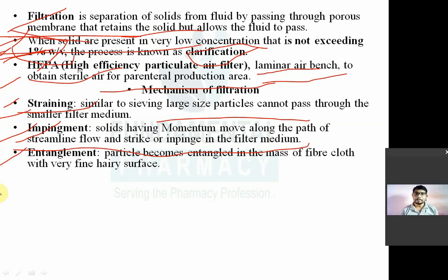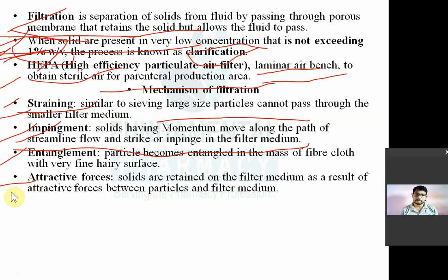So there may be attractive forces between the filter medium and solid particles, so that the solid particles will be retained on the filter medium as a result of attractive forces between particles and filter medium. So these are the four mechanisms for filtration.